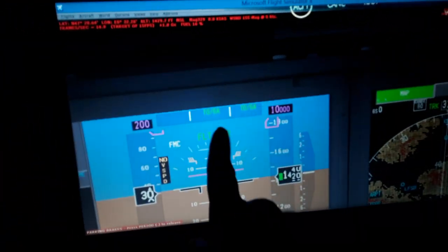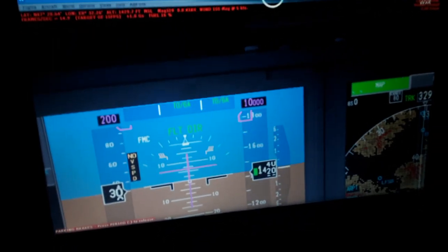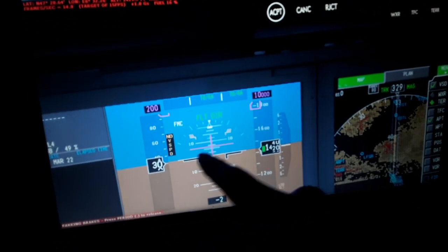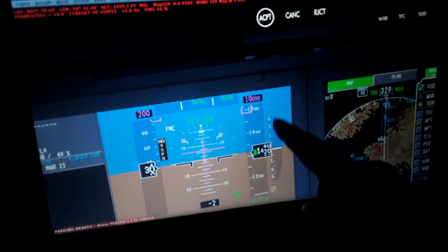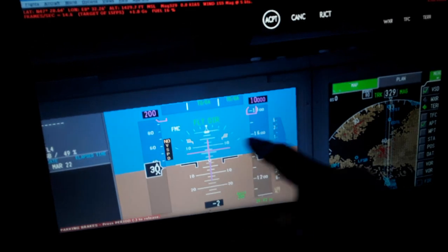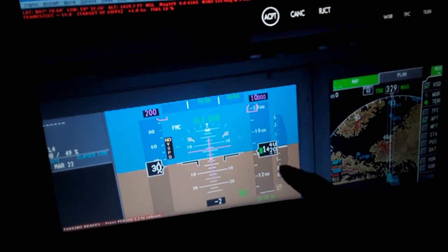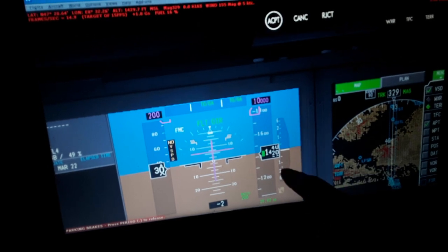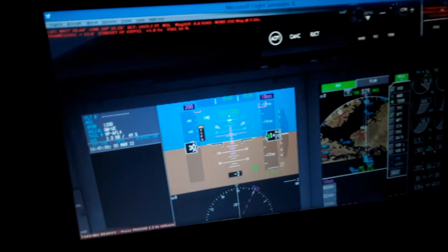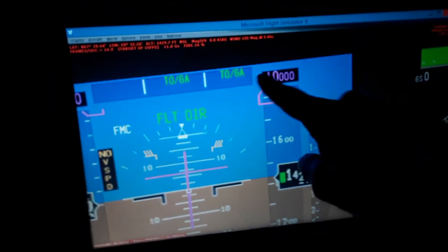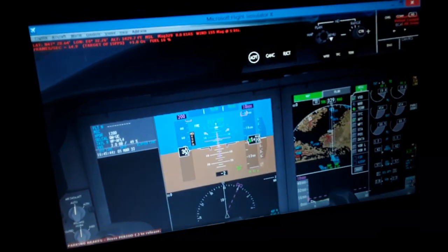So we have also the bank angle as the aircraft flies. You have to pay attention both to the airspeed; the pitch attitude in flight might be positive, but the aircraft might be falling instead. So you have to pay attention to all indicators: the airspeed, the altitude tape, the vertical speed indicator, and also the altitude indicator, the flight mode annunciator with the autopilot and the autothrottle, and the lateral and vertical navigation modes.